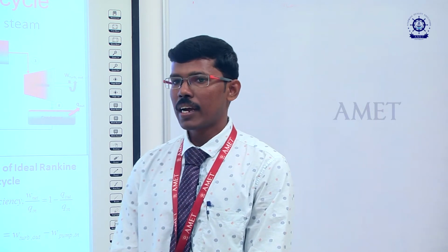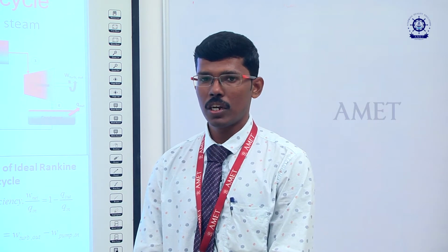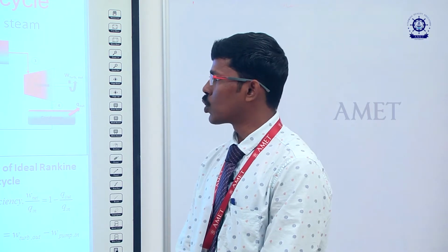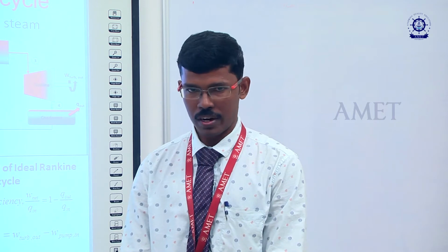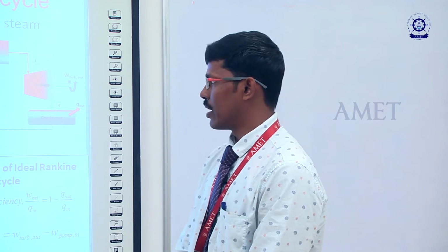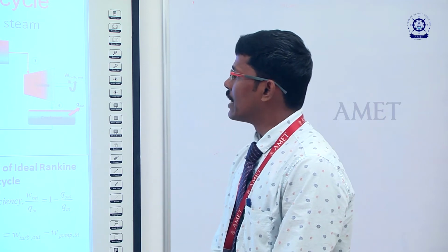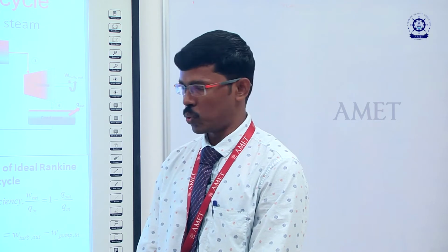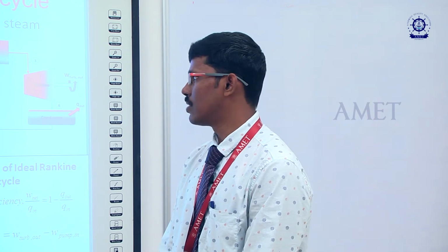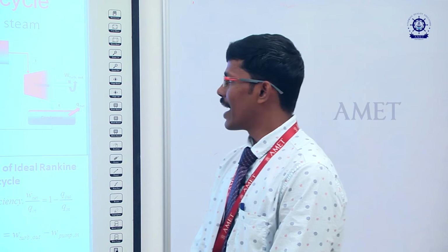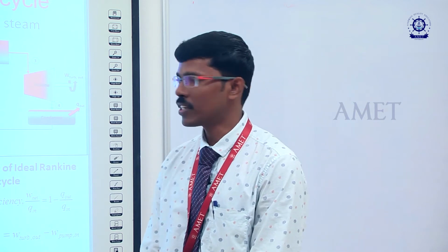Generally the kinetic energy and potential energy change of a vapor is very minimal compared to the heat transfer and work transfer, so it is eliminated from the SFE equation. The steady flow energy equation reduces to Q in minus Q out plus W in minus W out, which is equal to H at exit minus H at inlet. H is nothing but enthalpy.